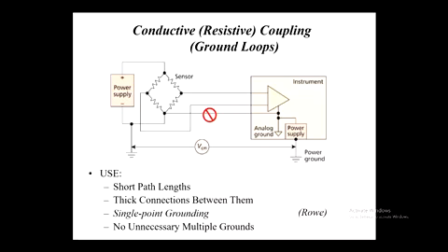That voltage is shown here as VCM. It's between two different points that are supposed to be ground, and sure, they're connected together, but if there's a big current flowing through whatever tiny resistance, there will be a voltage. That voltage will then appear as a common mode voltage between this point and that point, and thereby possibly get amplified in the amplifier.